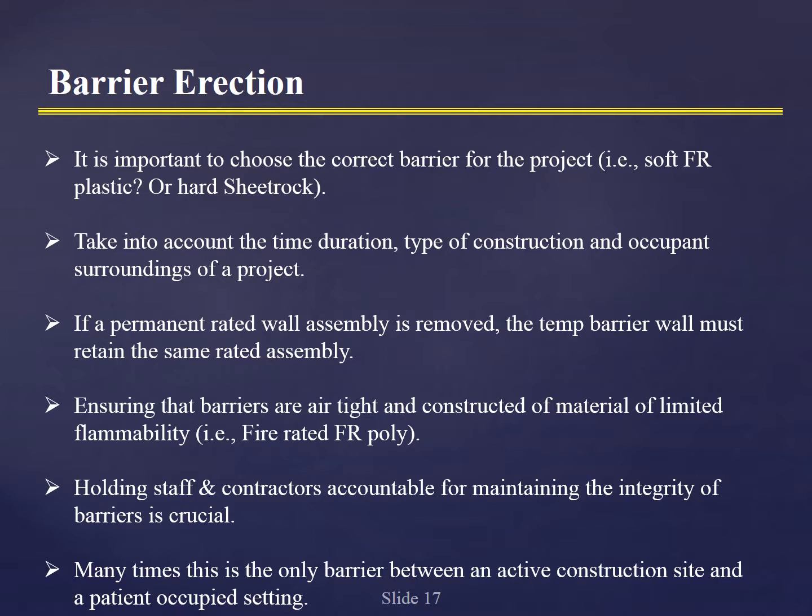Again, many times, this is the only barrier between an active construction site and a patient-occupied setting. So you have to make sure that those barriers, especially in that situation where it is the only thing between the construction and the patient, are solid. I saw a very large project like this recently where there was so much traffic and activity going on on the other side of a wall. In fact, it wasn't just on the other side of the wall. The whole wall was taken out, and it was a rated wall.